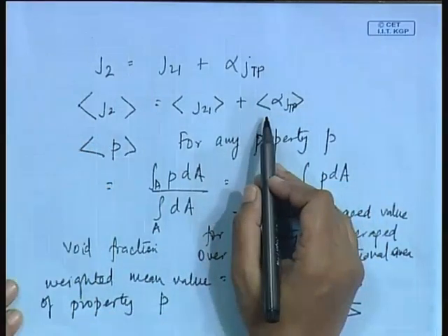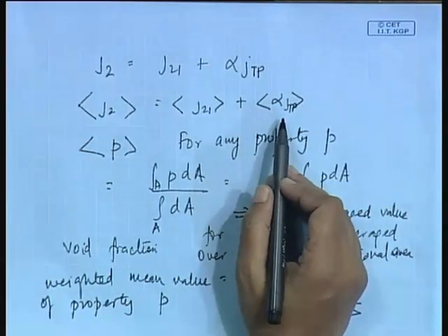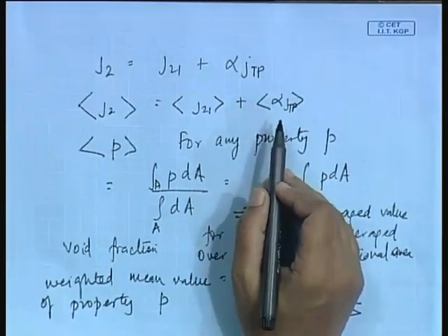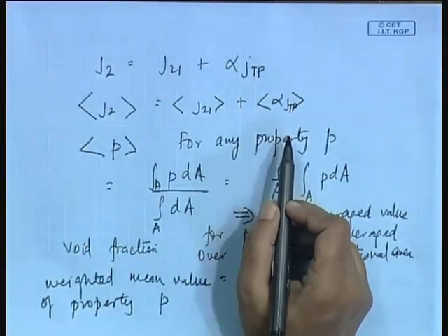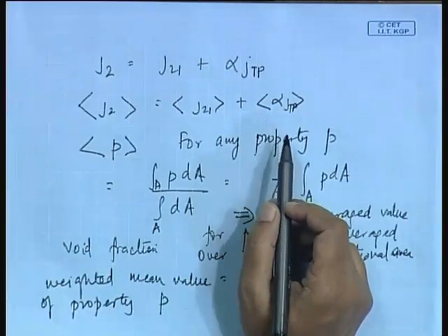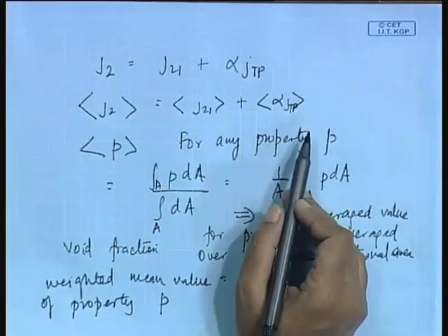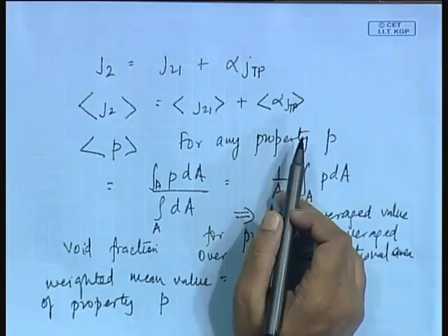From this particular model, now a very rational approach to obtain the 1-dimensional drift flux model will be to integrate the 3-dimensional drift flux model over a cross sectional area, and then we can introduce proper mean values. Okay. We can integrate this by using this particular formula over the entire flow field and over the entire cross sectional area, and then we can introduce proper mean values.